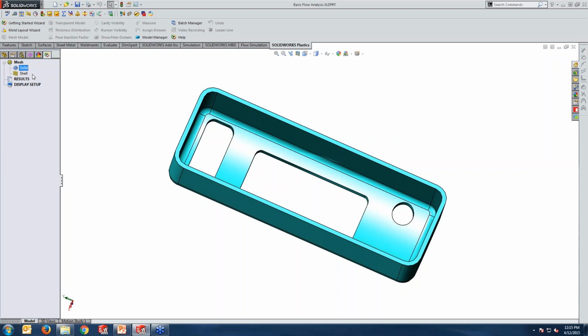But basically, you can understand now, using shell elements means you're just having one surface, therefore you have fewer elements. But if you're going through the thickness, that means you're using more elements. More elements, better results, and more accurate results in some cases, but definitely what is happening is it takes a lot of time. But when we're talking about shell elements, if they are valid, meaning we have very small thickness compared to the other dimensions, then they are super valid, they are all good to use, and you definitely have to define them and optimize the time. So it's better to have the answer within 10 minutes rather than 10 days.